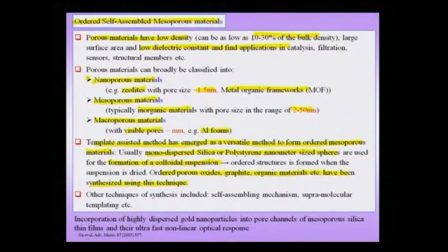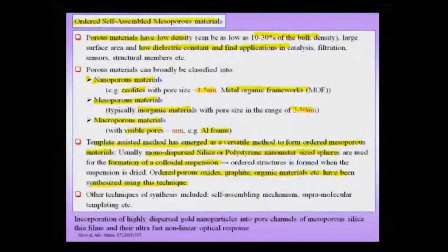There are other techniques also which have been used by people to assemble or self assemble mesoporous materials, and these include supramolecular templating and self assembling mechanisms, etc. Now, as I was mentioning, you may leave the porous material as a pore and use it, like for instance in filtration or catalysis, where you have a lot of surface area, internal surface area especially, which can be used advantageously in a mechanism like catalysis, wherein you really need a lot of surface area.